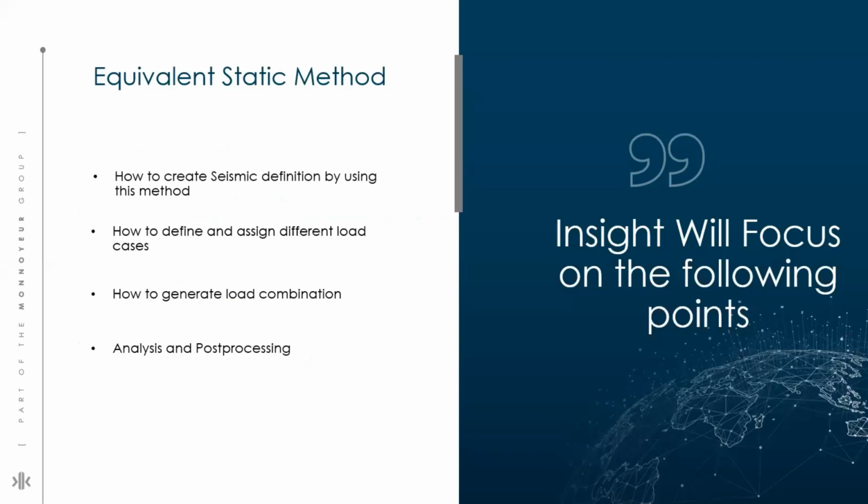In today's insight, we will be learning how to create seismic definition by using equivalent static method, how to define and assign different load cases, how to generate load combinations, and then I'll move to the analysis and post-processing part.